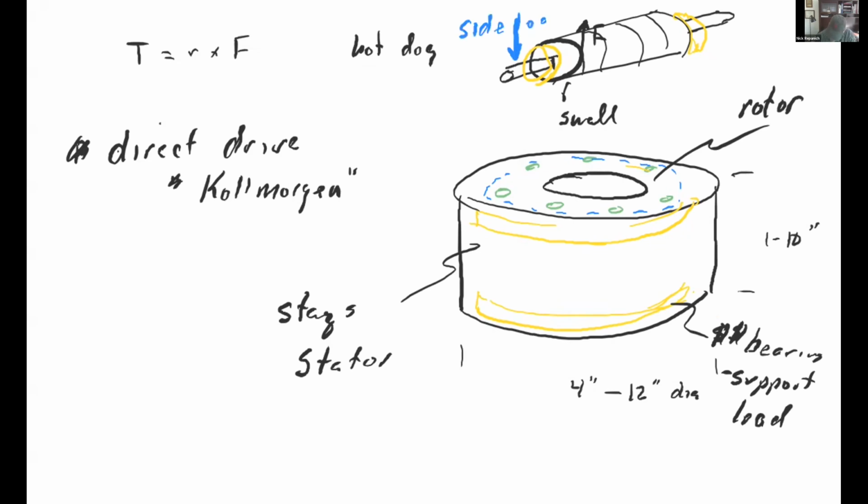Because if you think about it, as soon as you begin to rotate something, if you try and use the motor without a coupler and actually have the load move back and forth, like attach a belt drive right to the motor and move mass back and forth, this motor shaft starts to see that for every force, there's an equal and opposite force. If you're going to push the mass, it has to push against something, and the something ends up being the motor bearings. And these are tiny little bearings, and they're really designed only to spin the motor.